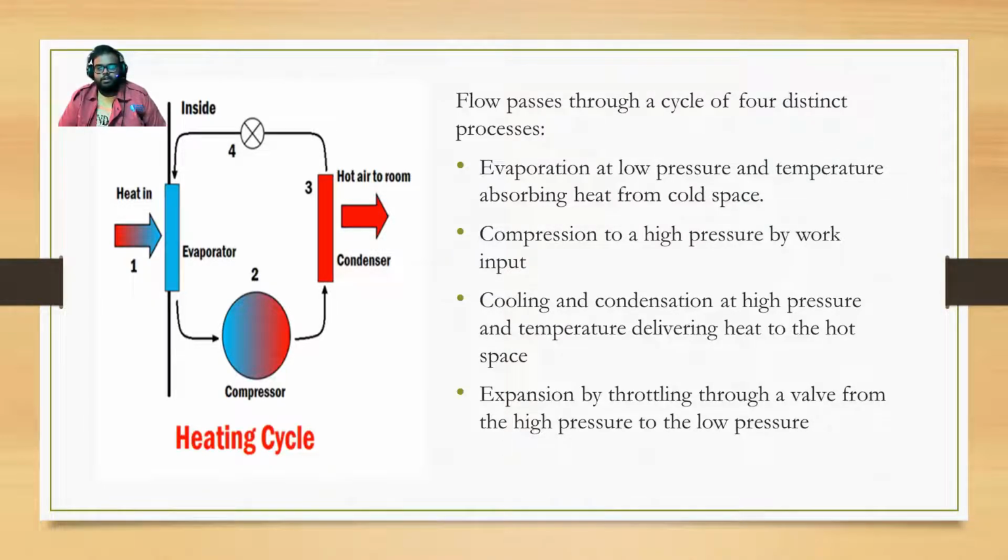Next, compression, where the flow is compressed to become high pressure by work input. Next, cooling and condensation at high pressure and high temperature, delivering heat to the hot space. Next, expansion by throttling through a valve from high pressure to low pressure.